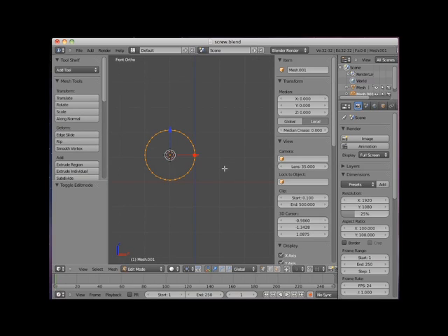The Screw tool has some very strict requirements. First, the screw operation must be generated in front view. Second, the subobject selection must contain an open polyline. That is, it must contain an open shape consisting of at least two vertices with an interconnecting edge. The screw operation localizes this open polyline, and it uses it to calculate the translation of the screw from turn to turn.